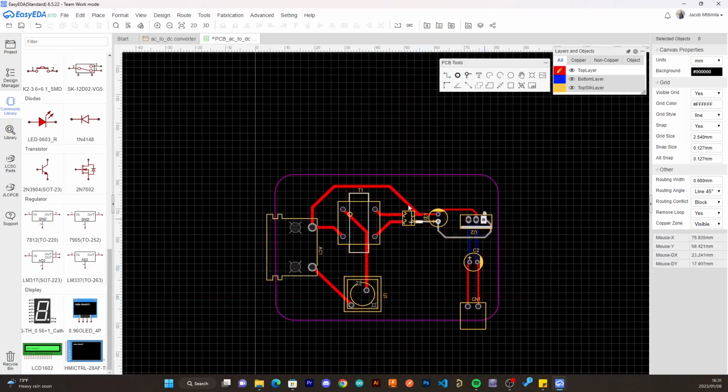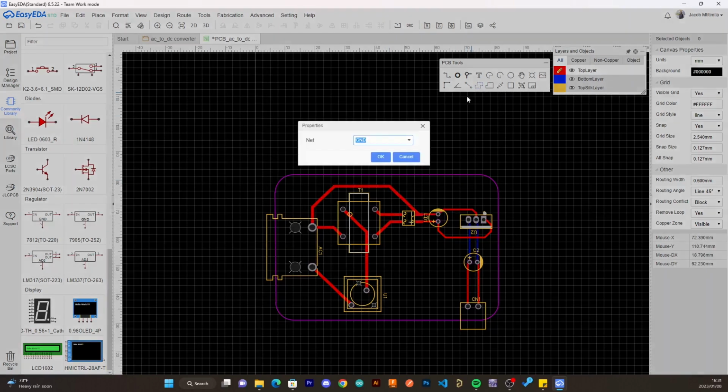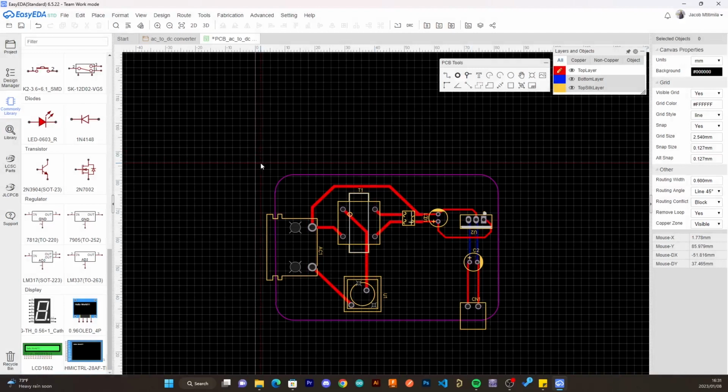There are some other complications that come in with just this orientation. You need to put a copper layer on the surface of your board in order to ground your board to reduce noise. In order to do so, we'll go here on our PCB toolbar, select our copper layer option, and you need to select the net to ground. So you say you are grounding the whole board. Select the outer part of the board in order to cover it.